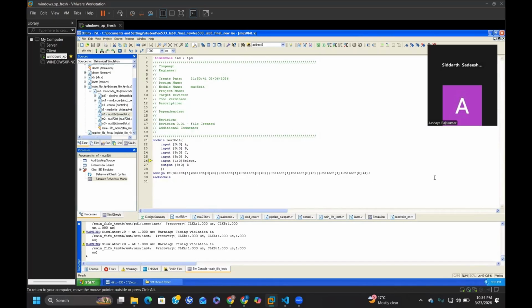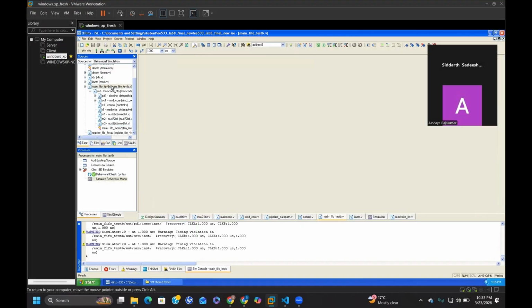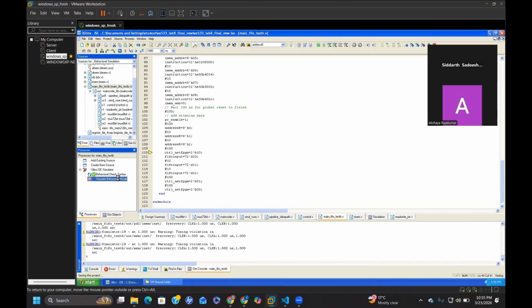Going on to the mux, it is again scaled up to get all three values, so it's like a 4-to-1 mux, for both 8-bit and 72-bit. The 72-bit is for our data. The NetFPGA data is about 72 bits: around 8 bits are for control logic, and the remaining 64 are the actual data. We have done an implementation for that, so we got the 72 and 8 bits for our address lines. That's the main stuff for our FIFO.